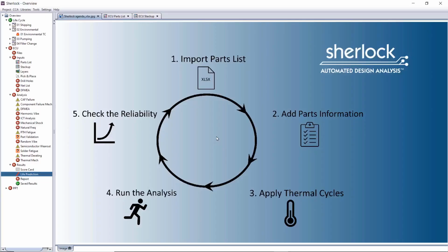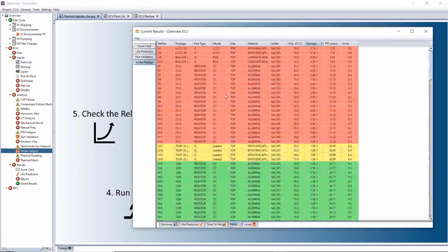It's an easy task to improve the reliability of our critical parts. Let us start with the 4 failing ICs. Of course, we can change the package type. This means extra cost, which I want to avoid. Better cooling could also be a solution. I keep that in mind when I position these parts on the board and place them at the outer edges. That should lead to a better cooling and therefore better reliability.